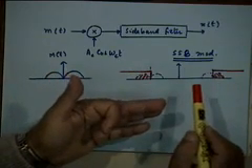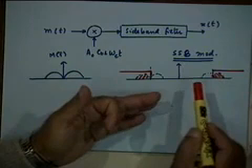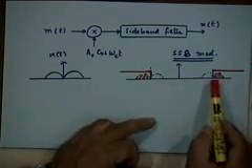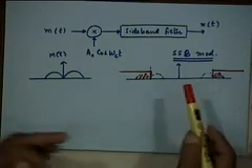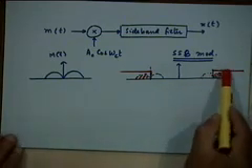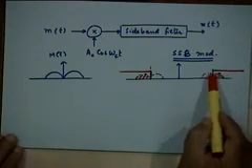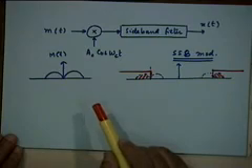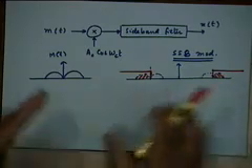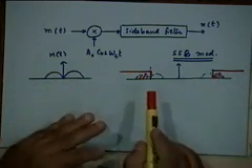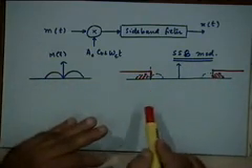In practice, we don't use low pass filters of such large bandwidth 0 to fc or such high pass filters, because in any case the signal has a finite small bandwidth. So it's more convenient to use band pass filters. But for theoretical discussion here, it is preferable to think in terms of high pass and low pass filters, as we will soon see.